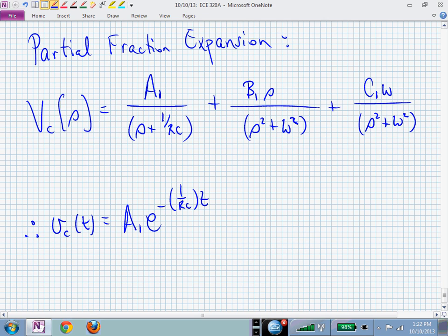Is that okay? That's just an exponential decay, and it depends on what I've picked for R and C. The middle piece, that immediately just falls out, doesn't it? That's exactly one of the rows in my table: S over S squared plus omega squared. And the other row produces this, and this is true once we hit 0.